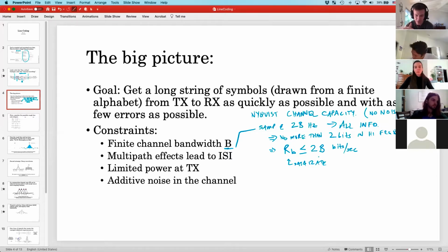If your bandwidth is fixed, there's nothing stopping you from amplifying the signal to multiple levels. And so we can actually modify this. For what are called M-ary signals, this always bothered me. It should be "Mary," right? But it's pronounced "emery": M-ary, binary, ternary, quaternary.